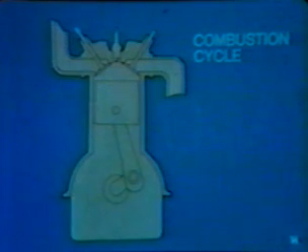The process of burning gasoline to produce power this way is called combustion, and it happens in a closely controlled cycle. The space above the piston, known as the combustion chamber, is fitted with two valves. The intake valve lets the air-fuel mixture into the cylinder before it burns, and the exhaust valve lets the burned gases out. An electric spark plug in the combustion chamber provides the spark for ignition at just the right point in the cycle.